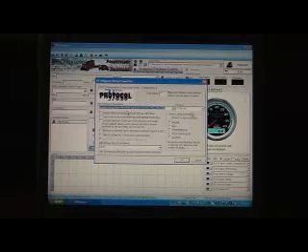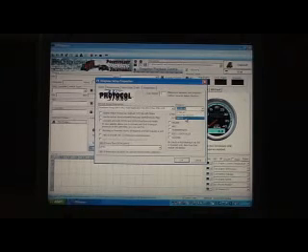The next step is the protocol. There are three choices: J1708 HD, J1939 HD and Industrial, or OBD2. J1708 is the most common protocol used in North American heavy-duty trucks. J1939 is a newer protocol, faster, and is only available in the more recent trucks, and in some cases with industrial applications is the only protocol available. If you try selecting with J1708 and do not get a connection, open the setup, change to J1939, and try again.